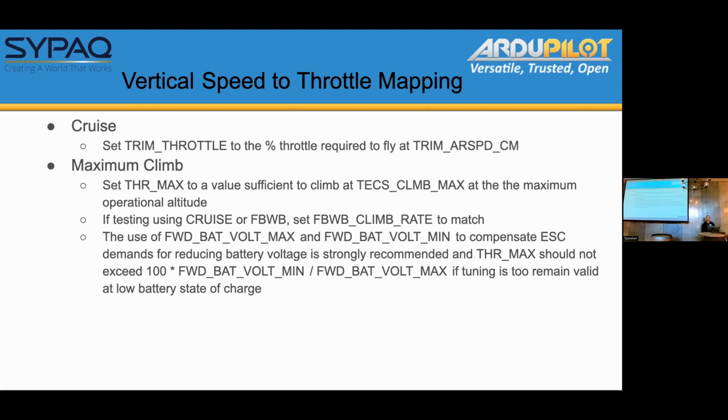Yeah. Now with ArduPilot, the comment was that with multi-rotors we have the throttle ESC thrust compensation thrust curve. Here, these parameters are optional. So you can set up a battery monitor, but you're not required to set a maximum and a minimum voltage.